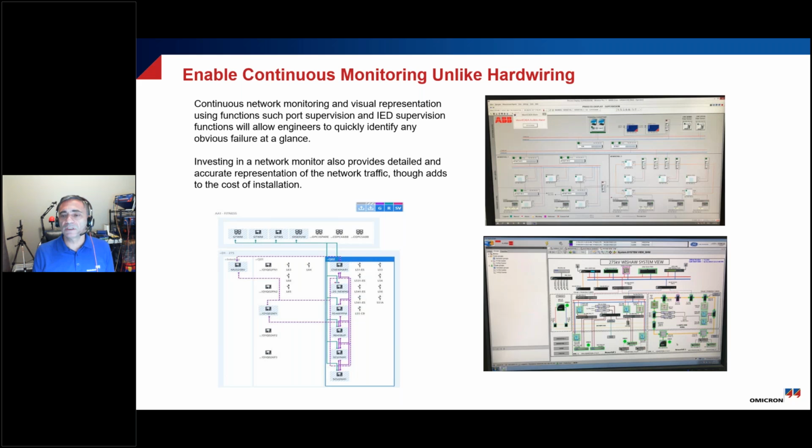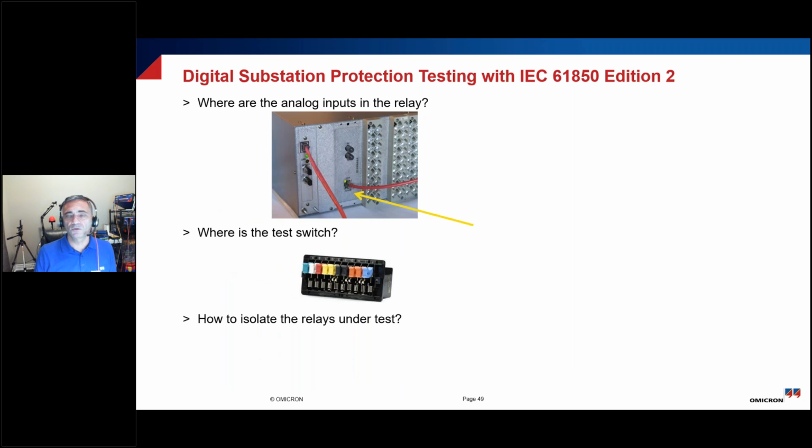You're also not only monitoring or controlling the process, but you're actually seeing the communications in real time. If there's a break in one of the links, it'll come up in real time and you'll be able to see that information. So you're monitoring your network, as opposed to an old copper network. If there's a problem with one of the connections or a contact, you wouldn't know until you needed it. Here, things are being monitored constantly. So it's a lot faster in terms of diagnosing a fault before you actually need that piece of apparatus. You know that there's a problem with it.